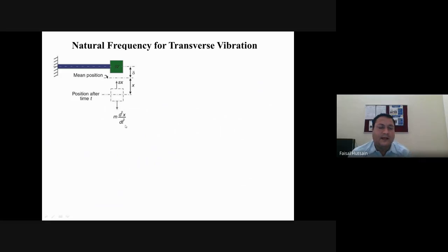See, in this figure there is a cantilever beam. It is fixed at one end, and a mass W is attached at the free end. As you can see, if I displace this body from the mean position, it will alternately bend. Now let us try to draw the line diagram. For example, this is your cantilever, this is your shaft, and this is your mass.